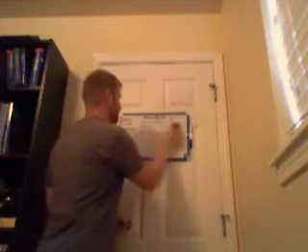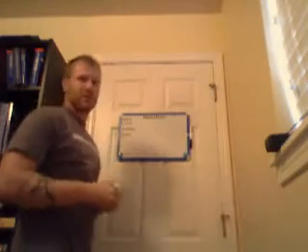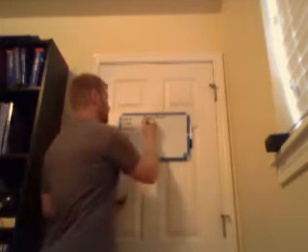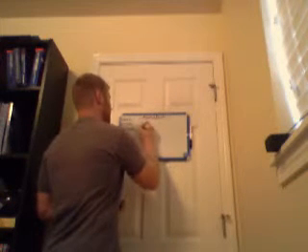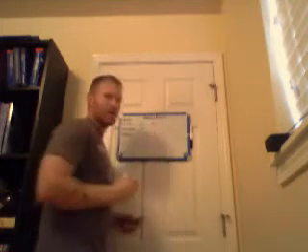So we can do a practice calculation here with just a simple number. So if we have our weight, 50 pounds, our arm, distance from datum, let's just say 10 inches.